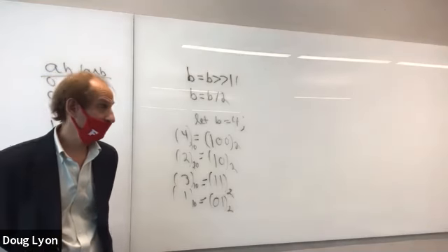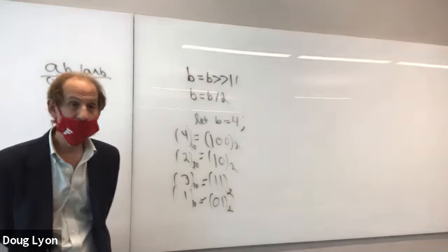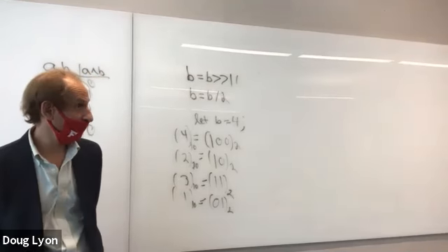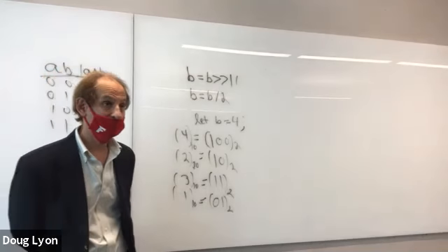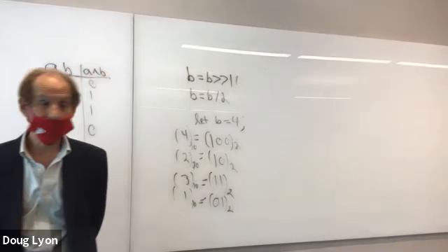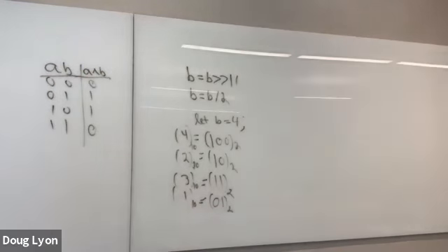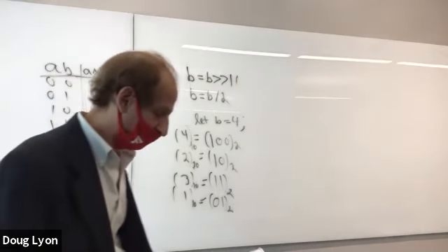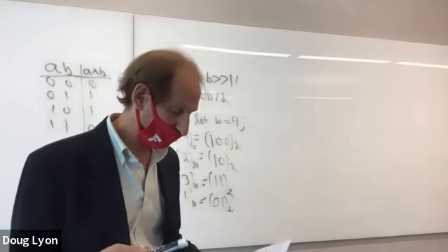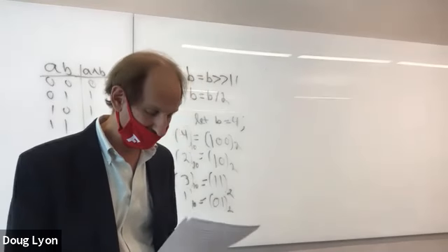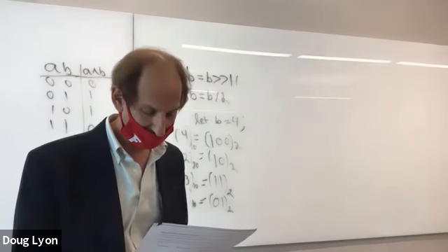And 154 cycles at 8 megahertz for that machine meant you couldn't do it faster than 8 megahertz divided by 154 clock cycles. That's how fast it would run. And so you had to take that into account when you were attempting to do real-time control or filtering. So sometimes it takes a little while to do those more extensive operations.